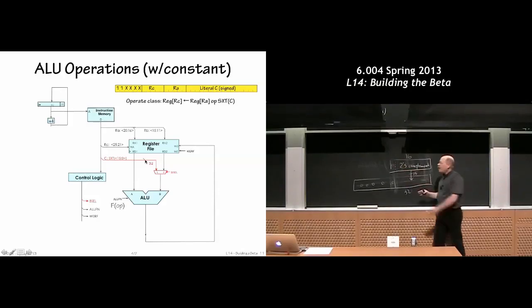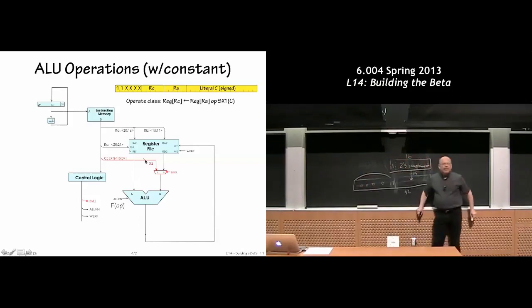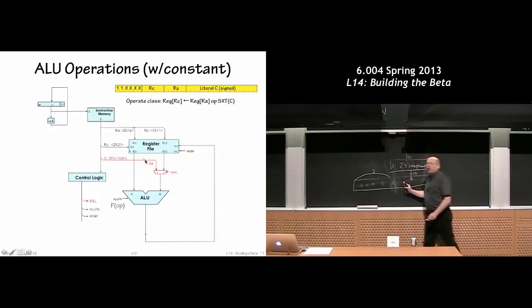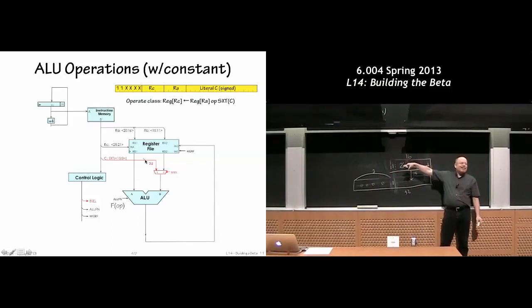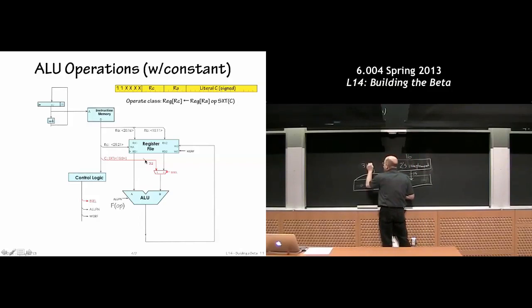When this number is negative, what do we do with these high order bits? We make them all 1s. Because that would be the 32-bit representation of the same integer, with high order bits all 1s. The reason it's called SXT is sign extension. This bit basically gets copied not only to the 16th bit of the constant, but also bits 31 down to 16.